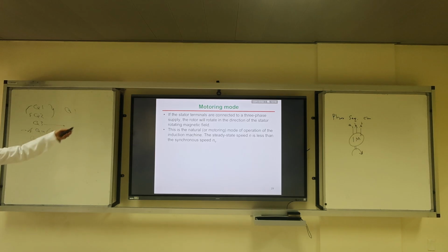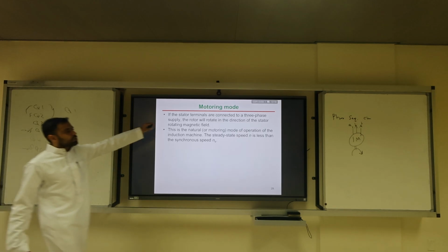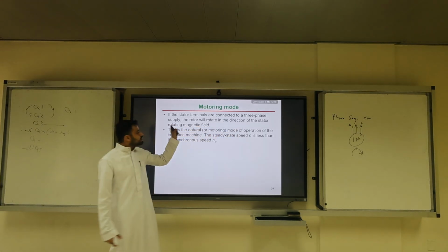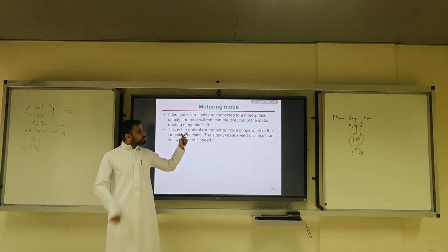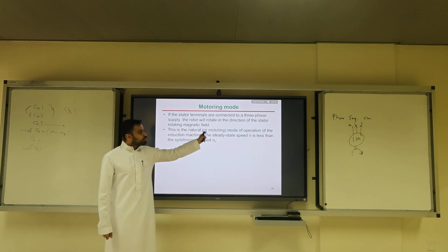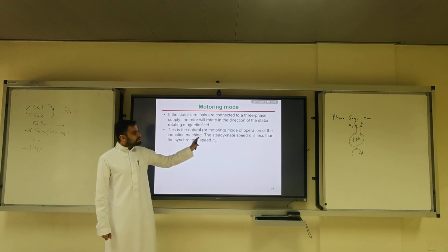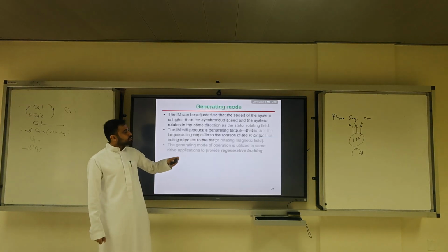The motoring mode: if the stator terminals are connected to three-phase supplies, the rotor will rotate in the direction of the stator RMF. If you flip the direction of RMF, then the speed will be the opposite. This is the natural motoring mode of IM, steady state speed N is less than the synchronous.